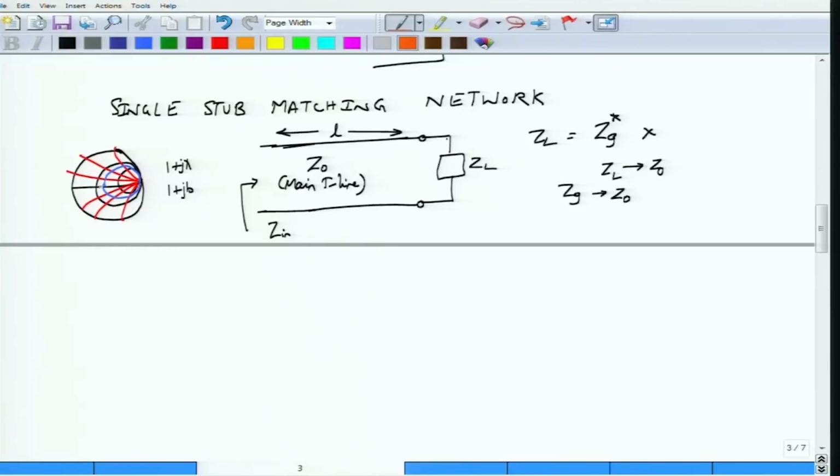So with this unit circle in place, what we would like to do is to take any load which is described by a certain SWR circle, upon which this would actually be propagating. Since this color is not very nice, let me redraw this particular thing. Let me write the Smith chart in this way and write down all these constant X circles. Let me write down the unit circle, that is the unit circle which I have drawn. And now this is the SWR circle. At some particular point there is a load here.